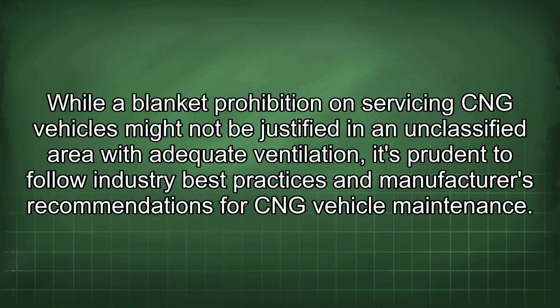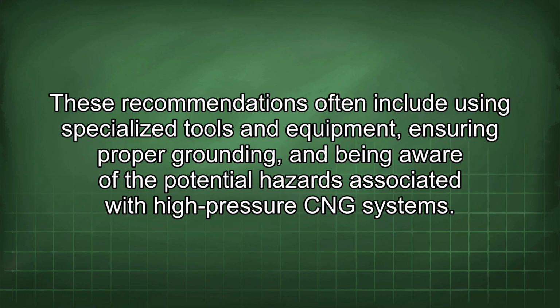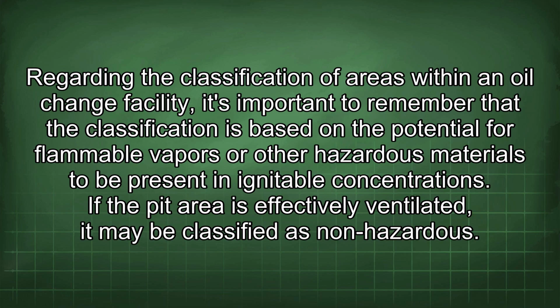While a blanket prohibition on servicing CNG vehicles might not be justified in an unclassified area with adequate ventilation, it's prudent to follow industry best practices and manufacturers' recommendations for CNG vehicle maintenance. These recommendations often include using specialized tools and equipment, ensuring proper grounding, and being aware of the potential hazards associated with high-pressure CNG systems.